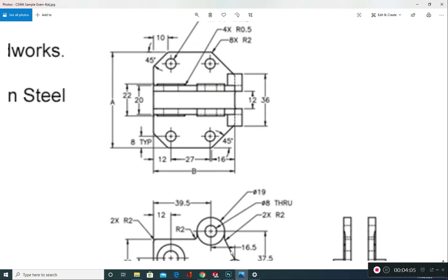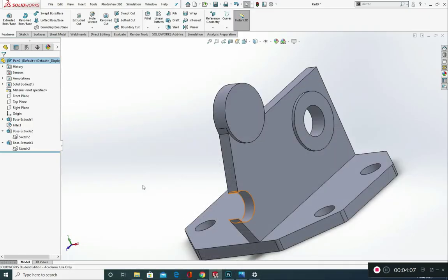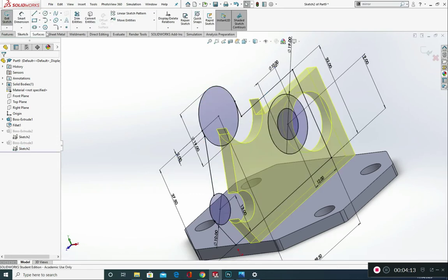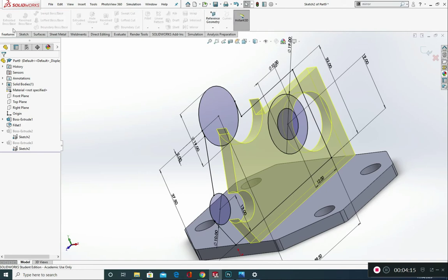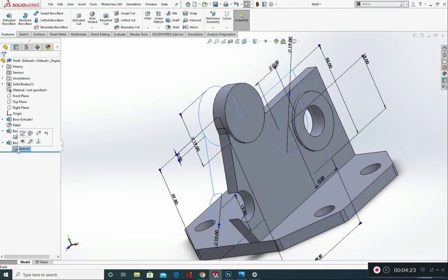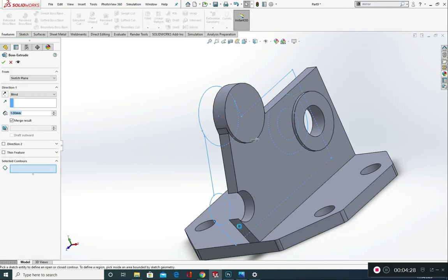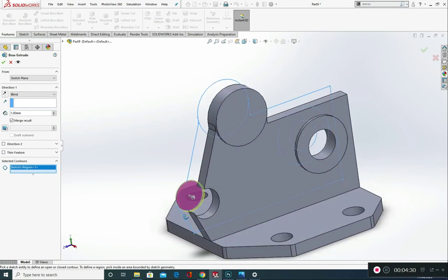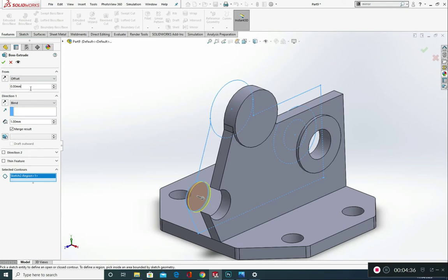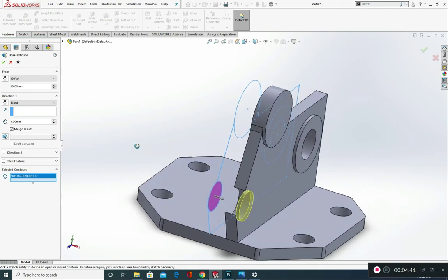Okay, so into SolidWorks, sketch, edit the sketch. We want to make a feature. Oops. Okay, sketch, not edit sketch, just click on the sketch and extrude boss base. I want to pick up this feature this time. We want an offset again of 10mm, like so.